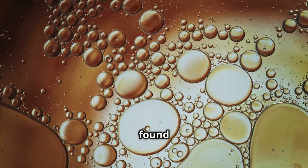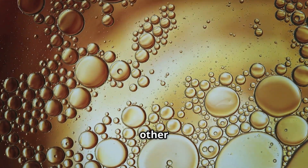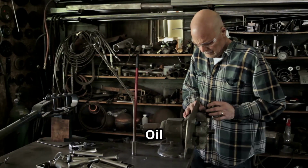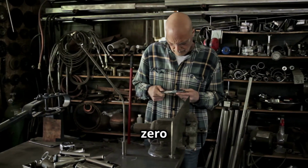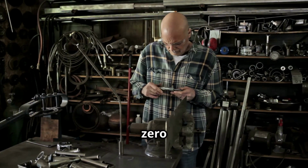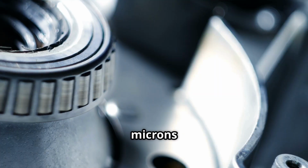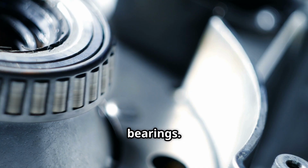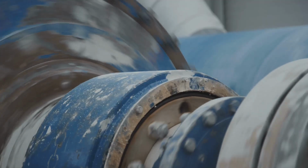Any friction remaining is found within the lubricant itself as the molecular structures of the oil slide past each other during operation. Oil films are typically in the order of 2 to 100 microns, 0.00008 to 0.004 inches, thick. They can be larger, around 300 microns or 0.012 inches, in very large diameter journal bearings. Lambda values, which are the oil film thickness to surface roughness ratio, are usually greater than 2.